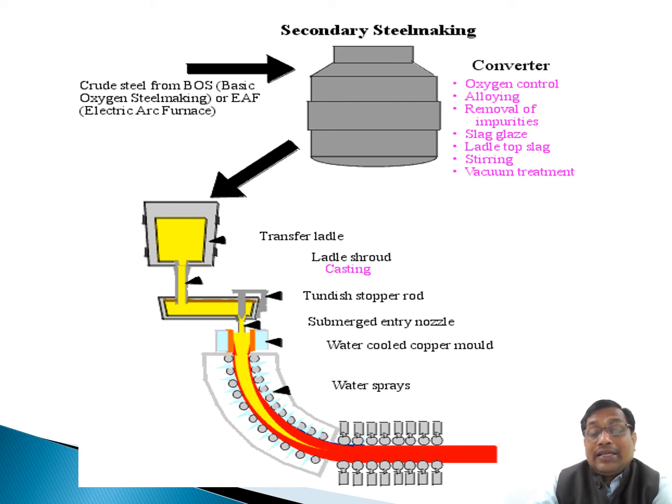And here a technical thing is there, you have to mark. Suppose a cutting torch is stationary, it is cutting at a particular spot. Suppose we are using a gas torch, it is focusing upon a particular point, but this bar is continuously coming out, so the focusing point may change anytime, and our cutting may not complete.